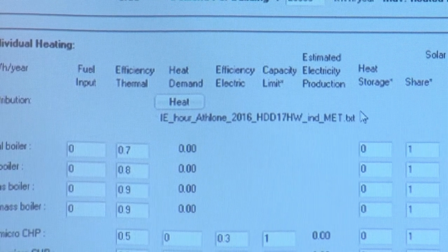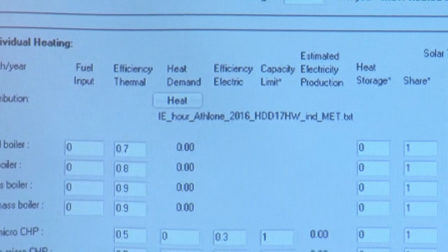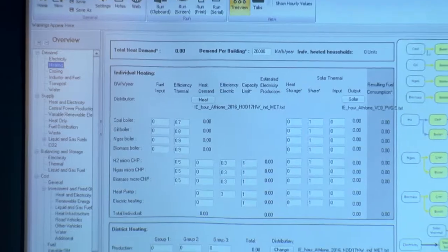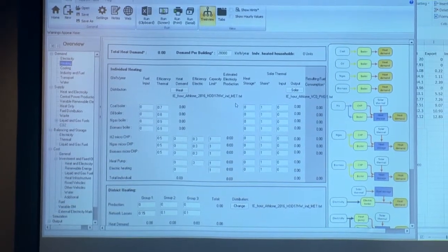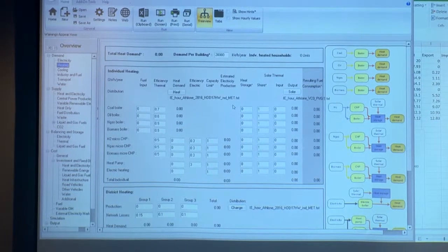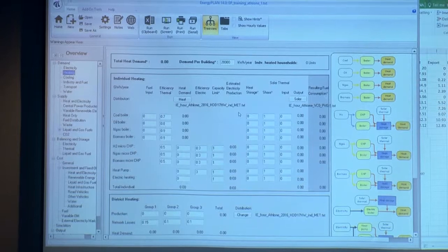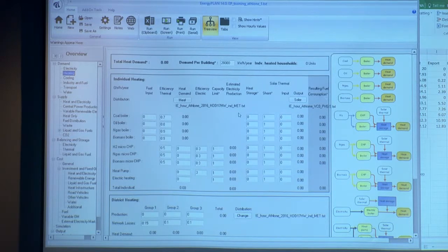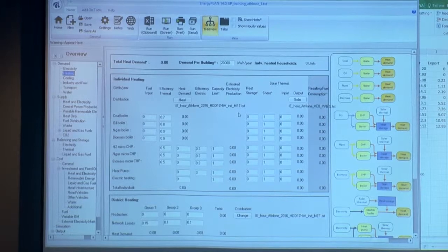So if you have that, then you are on the right track, and that actually shows you how the heat demand is distributed over the year. We have had a look before at that. We don't look it up. You know, it peaks, or the higher parts again in the winter months, and then it drops during the summer months. It doesn't drop down to 0 because we have included the hot water demand, which is about 20% of the heating energy demand.